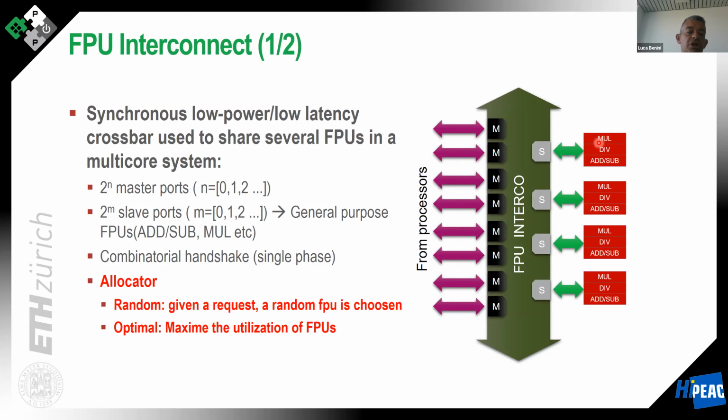So here we use, for example, random arbitration, which essentially means that you map the request to the unit that is available, and you choose among the multiple requests randomly to avoid privileging a single core, and at the same time, thanks to the randomness, spread out the accesses to several available targets if there are several targets.